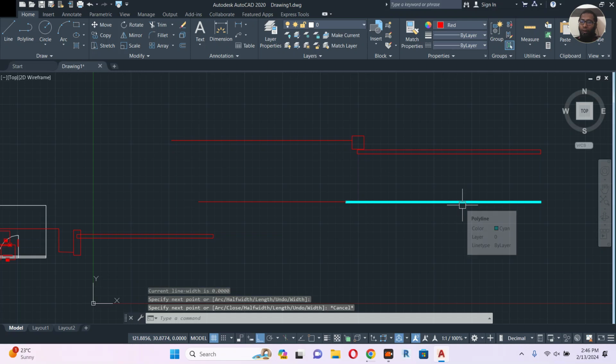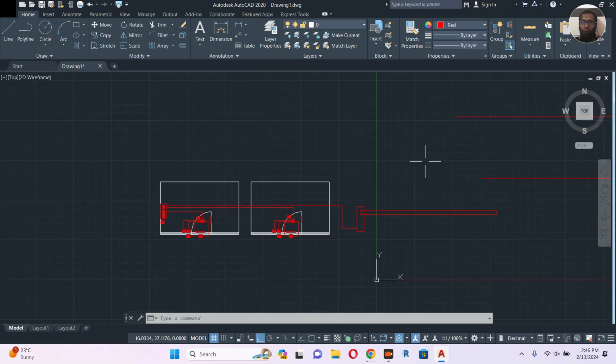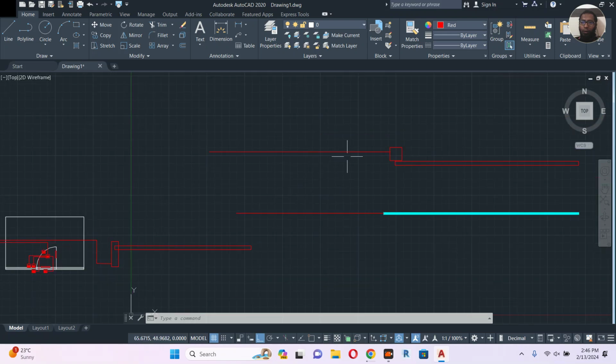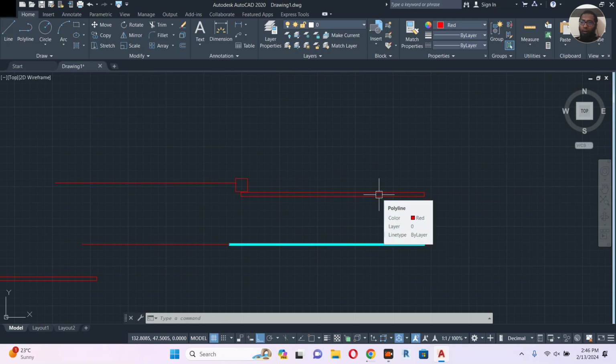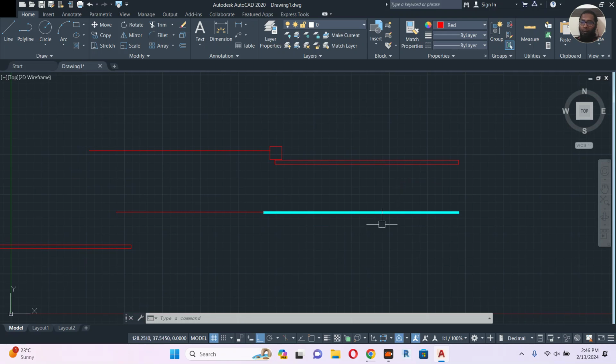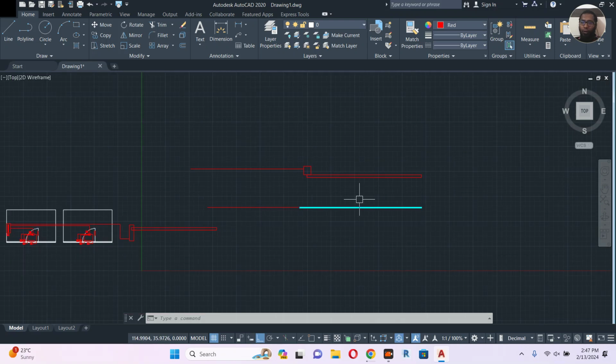If they already have the card, it will sense and then give a signal to the control panel. From the control panel it will give the signal to open for a certain time period. Maybe when the sensing is disconnected, it can be closed. This depends on the programming.